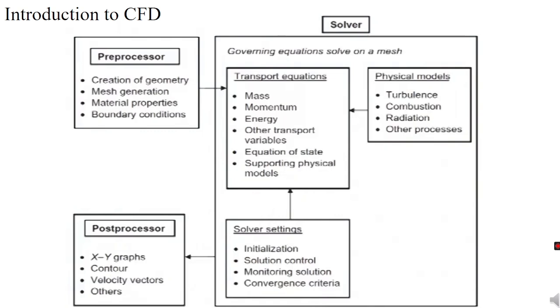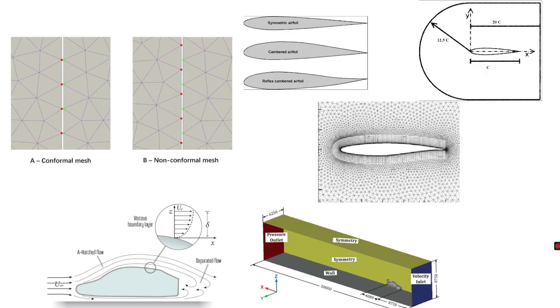For external flow, we need to create the domain external to the object. Like if we take the example here, this is the aerofoil shape we have, and whatever flow behavior we need to understand over the aerofoil, we need to create the domain. In this case, this is external flow. While doing the analysis, within which area we need to see the effect or the behavior of the flow over the foil, we need to create the domain, and within that domain there should be the aerofoil shape.